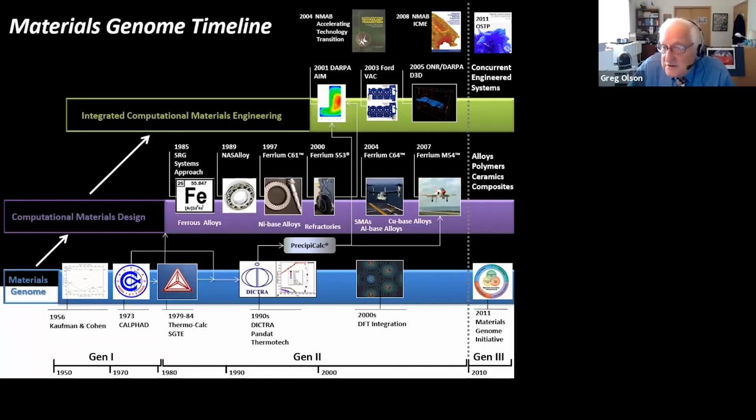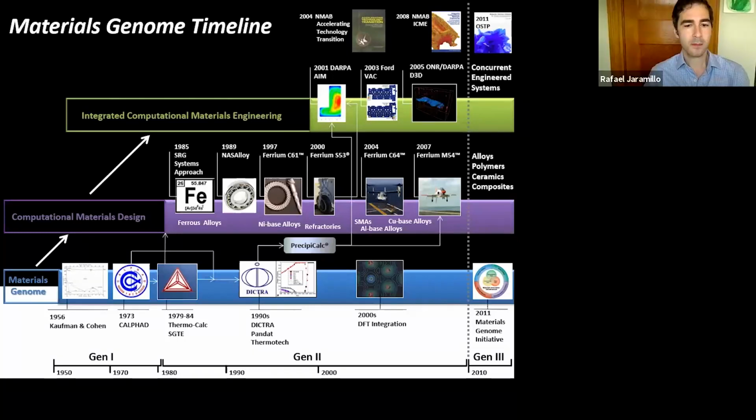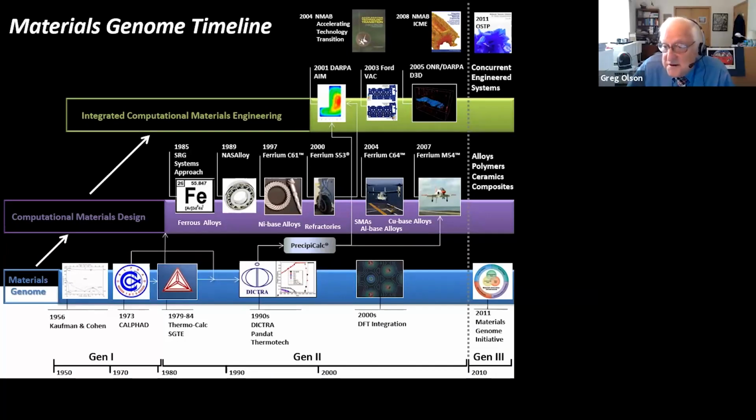I'll come back to it a bit later, but the big challenge is that the high chromium levels that you need to get the corrosion resistance are in conflict with the things you need for the mechanical performance of strength and fracture toughness. And it was a matter of using a predictive science approach to take it to a higher level of optimization that could resolve that conflict. That wasn't going to happen by empirical development. And I'll illustrate what was key to that later on.